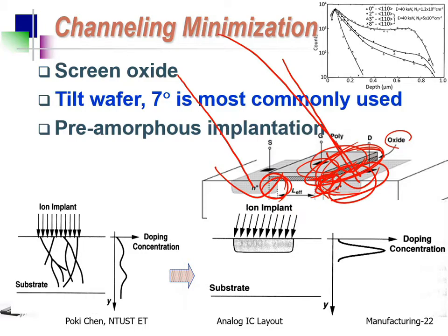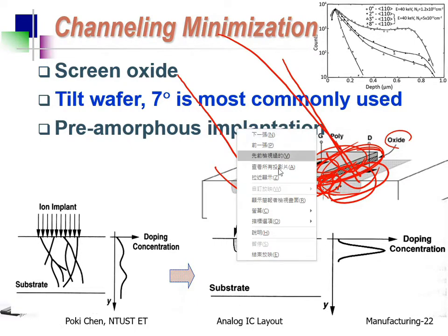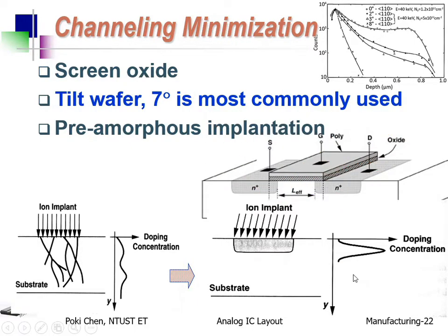Okay. Maybe right. I'm an IC designer. Who cares? You need to care, especially for analog IC designers, because for your simulations, whether pre-sim or post-sim, you have one assumption, even from the best IC fabrication company, TSMC on Earth. What kind of assumption? The source and the drain are symmetrical. Their properties are exactly the same during your simulation, but for fabrication, sorry, they are not the same.